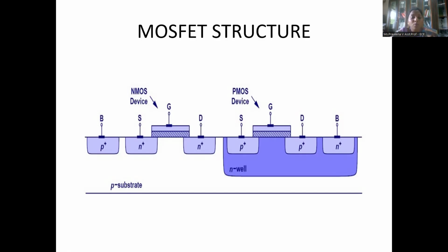Okay. Why are NMOS and PMOS used together? In a CMOS circuit, NMOS transistors are good at pulling the output low, and PMOS transistors are good at pulling the output high. So only one transistor conducts significantly at a time, which results in low power consumption.